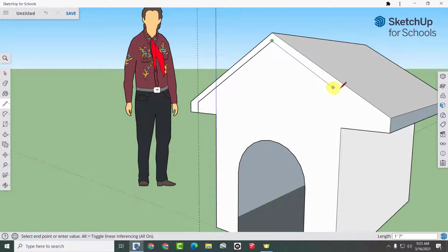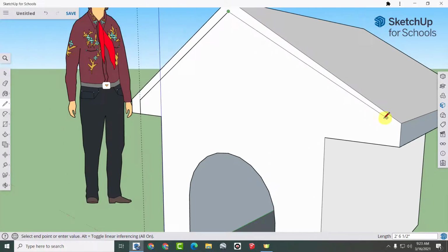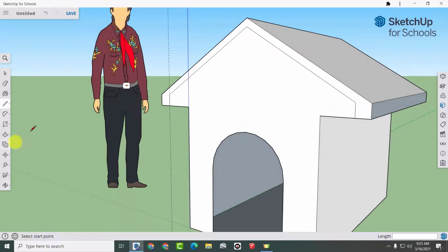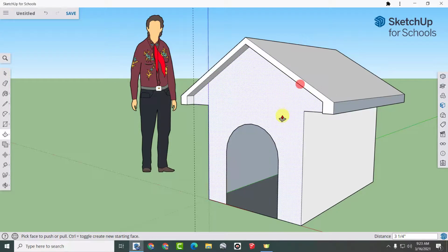All right, now we're going to carefully move down the other side. We're going to hover over this line again. It's going to give me a parallel line somewhere. If I hover, and there's my parallel edge right there. I'm going to move down that parallel line until I get to this corner here. I'm going to hover and then move straight out until I connect with the pink parallel line again. All right, there. And I'll click, move down, and pull out.